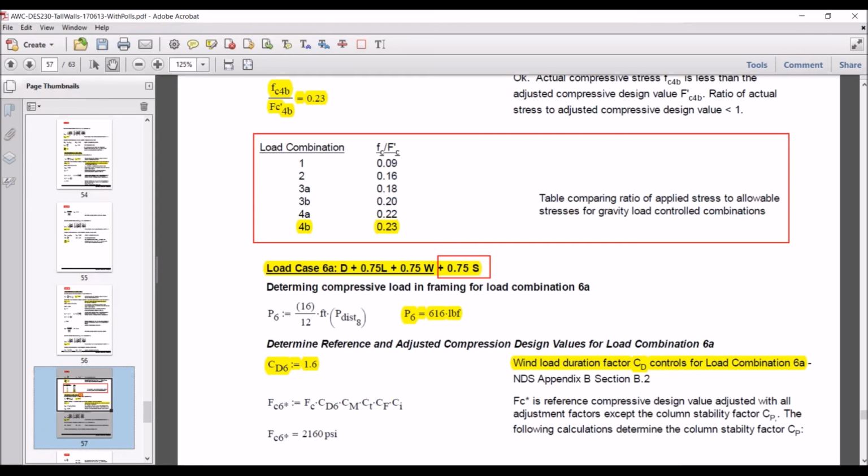But hopefully what you're seeing here with the wood frame construction manual tables, and if you look at the load combinations in your area and the wind loads that you have, you could maybe run some analysis and come to a comfort level that you can design a lot of your studs with these C&C loads, and that's going to control a majority of the time. Now, WoodWorks has software.